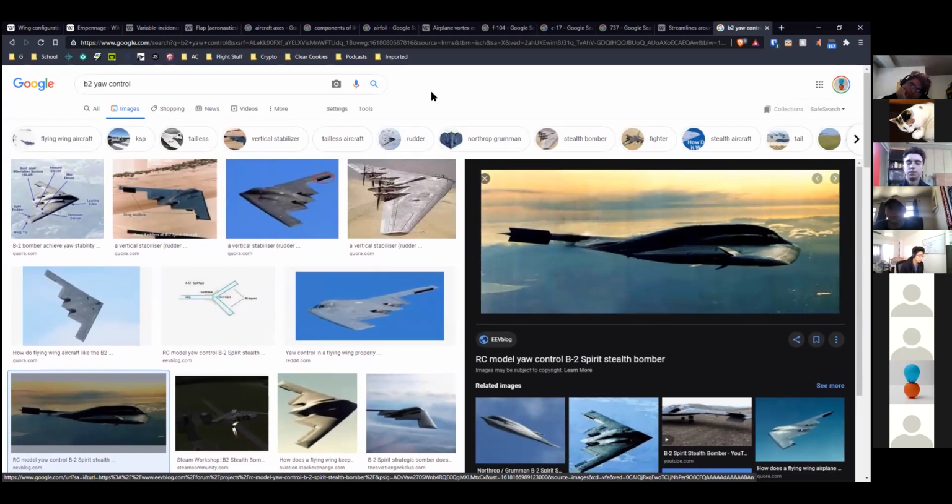They can be varying levels of direct authority. In really old school planes, and even some current planes, if you move the thing that changes the pitch, it literally moves a bar or a cable that's directly linked to the elevator and turns it, or the ailerons and turns them, or the rudder and turns it.